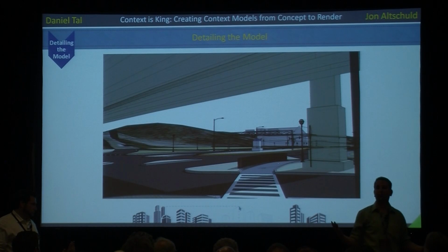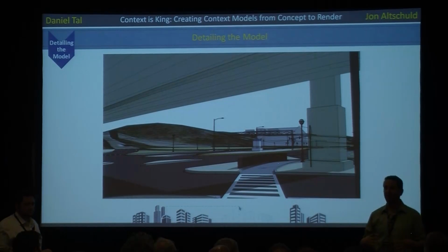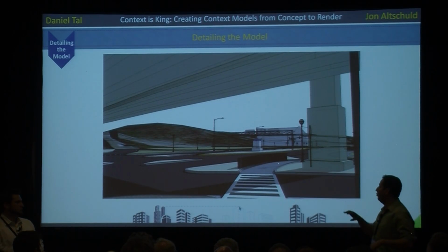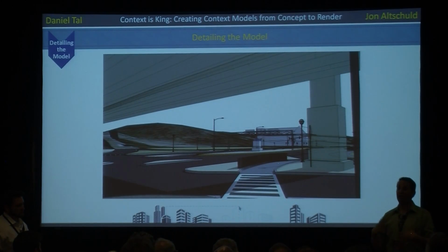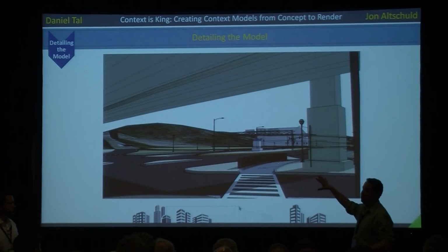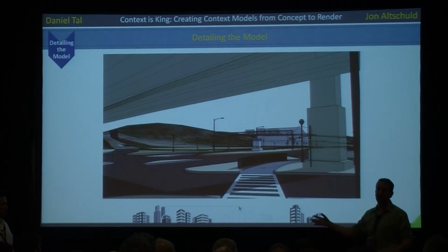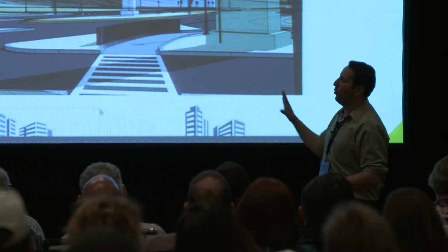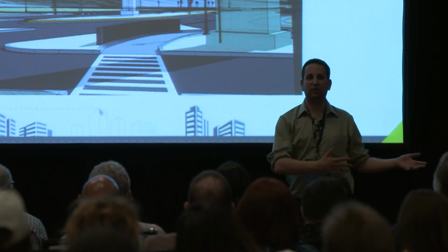So there's times if we're experiencing a lot of lag because the file size or the model geometry size is too big, we will try and remodel some of those components to actually make them less polygon intensive. Because ultimately, if you take a component that's got 100,000 faces on it and you put 10 of them in your model, all of a sudden you have 1 million faces in there. Going in and reducing it will save us a lot more time than render.